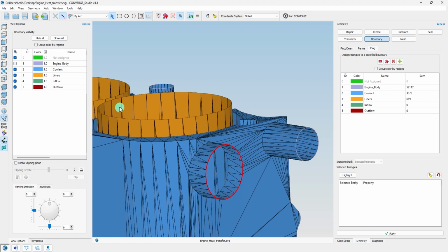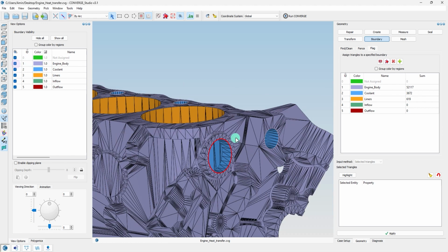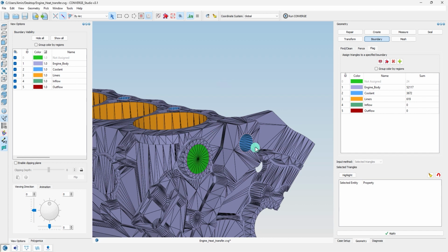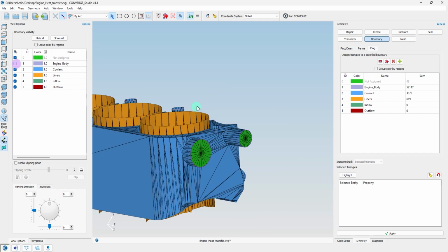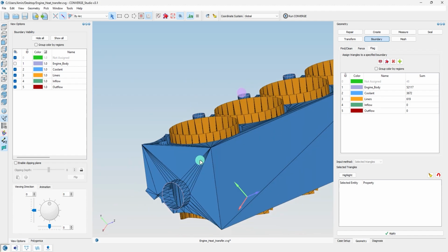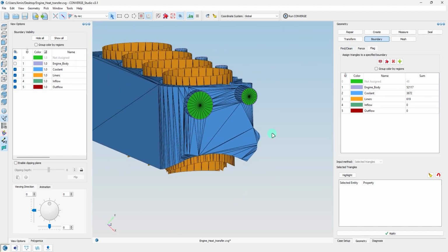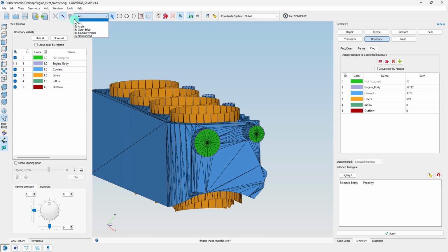Also for non-circular places, you can use P for patching using the selected edge loop. These do the same job, but you can have organized facets with the O key. It's better to specify the names of boundary after each patching.